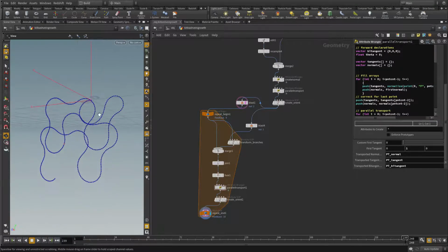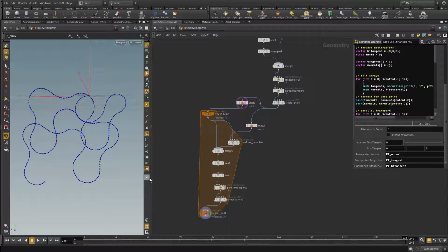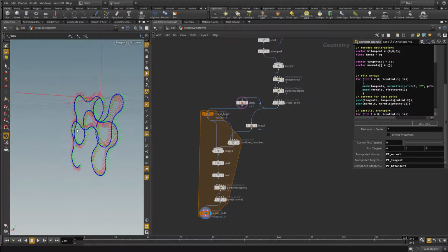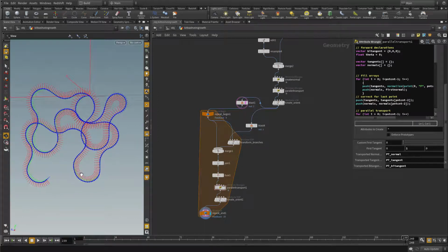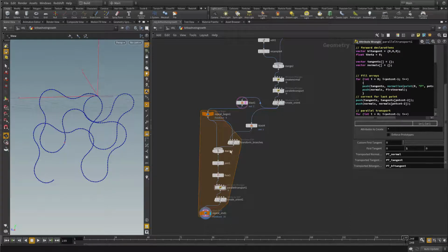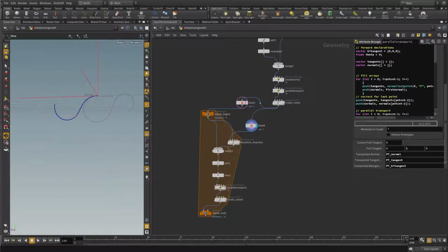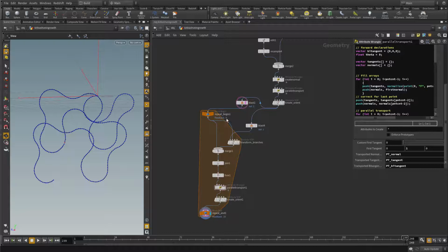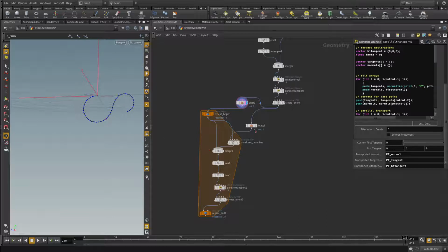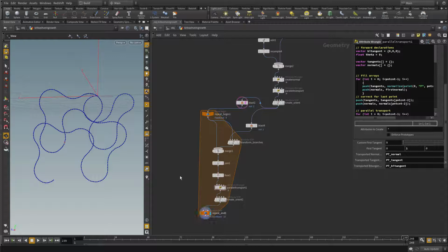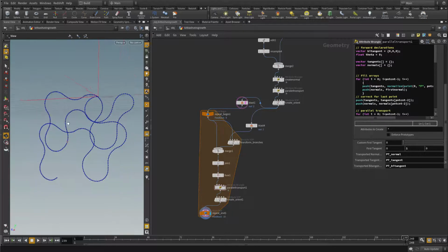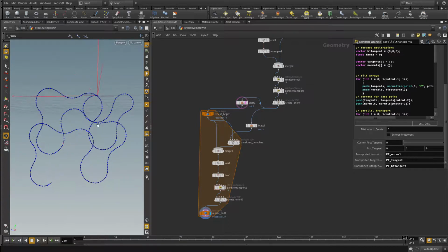And we get this. If we click on the visualizer for the orient attribute, you see we have a now quite complex curve. And this complex curve has a nice curve framing. So what happened here? Well, 10 times this primitive here is appended and appended to the end of the spline that is created. So it starts with this primitive, then appends 10 times this primitive to the end and creates a new spline with new curve framing. And the result is this nice looking, interesting spline.